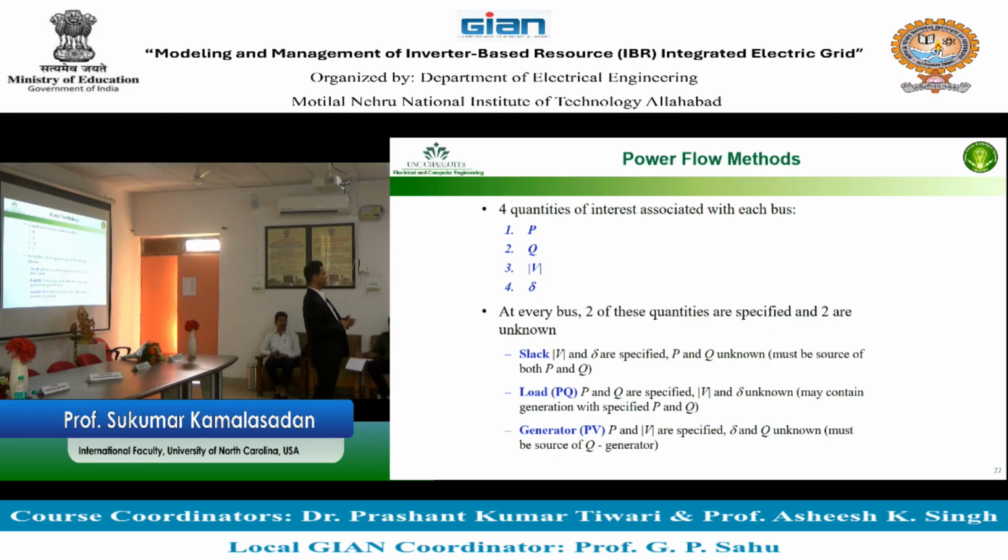Okay. What are the other things you should know to solve the power flow? We can actually solve it by looking at it here. There are two ways you can write the power equations. Everybody knows that? Complex power S is V I conjugate. In fact, three ways. Can I write apparent power in another equation? V square divided by Z. Is there another equation, I square times Z? These are three different ways you can write the power.